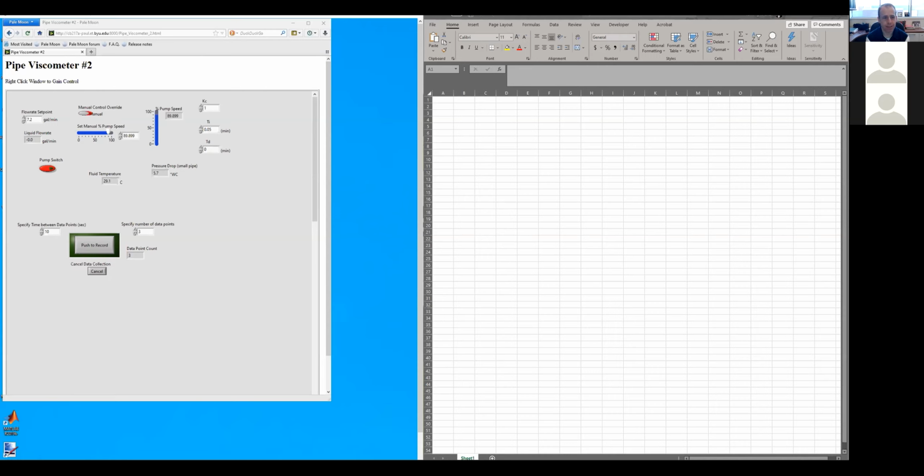And that usually happens with a gas. It's very hard to get a Mach number of 0.3 if you're flowing a liquid. If you're flowing a gas, it's actually pretty easy to get above Mach 0.3. And you always assume it's compressible. Almost. And so you want to be aware of that.